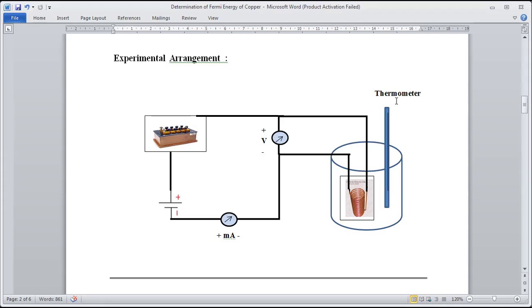In this way, you can connect. And after that, the water is heated in an electric kettle to its boiling point. Once the water starts boiling, you have to pour it into this beaker, switch on the power supply, and unplug some keys here to connect a small resistance. This small resistance is needed to control the current, because the resistance of the copper coil is very low. If it is not there, the battery may get shorted. So that is the problem.